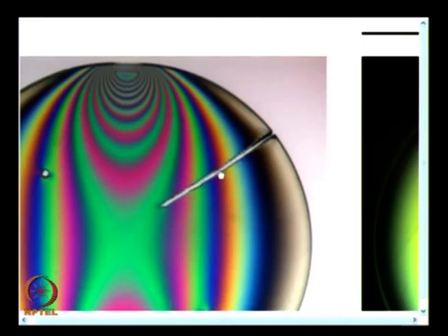And similarly, if I do the slicing properly, suppose I make another cut here, I will have a slice like this. So, that slice will retain the original stresses that have been locked. So, when I do a machining process, I must take sufficient care that I do not introduce any kind of machining stresses, and you have to also have a coolant, so as to take away the heat, and you use a single point cutting tool. There are many restrictions on how you do it, and you need a mechanic to be trained to handle these kinds of problems. They will use a high speed, single point tool, and then minimize generation of machining stresses.